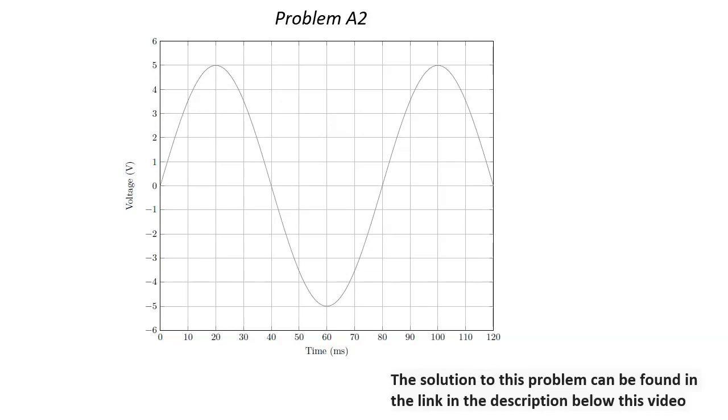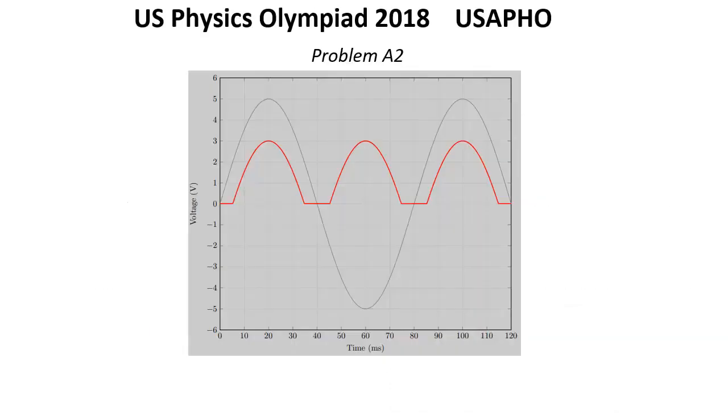So that's the answer sheet. Solution for question B. When the absolute value of VAB is less than 2V0, no current flows. When the absolute value of VAB is greater than 2V0, current begins to flow, with each diode subtracting a potential difference of V0. Note that the current flows in the same direction for both positive and negative VAB. This device is a rectifier.